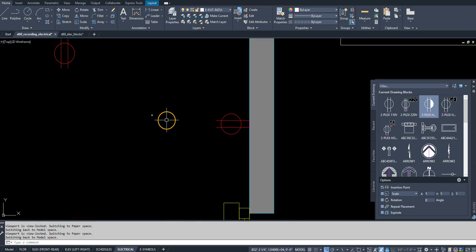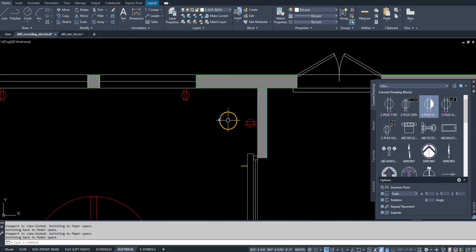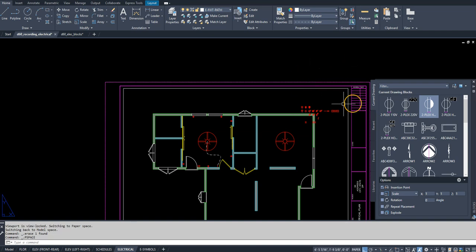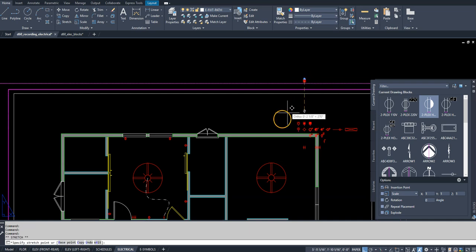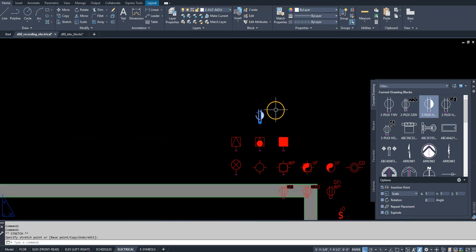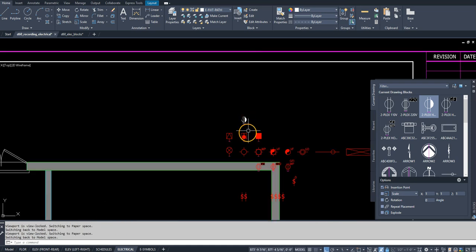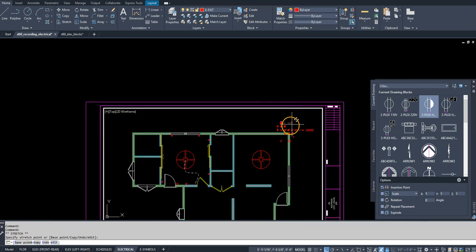It'll come in small if you're in the viewport, but if I'm outside the viewport and I drag and drop it into paper space, then I can come over here, move it in front of the viewport, change space, highlight it, hit enter, it comes in there, and then I can just match properties so that it's on the right layer.